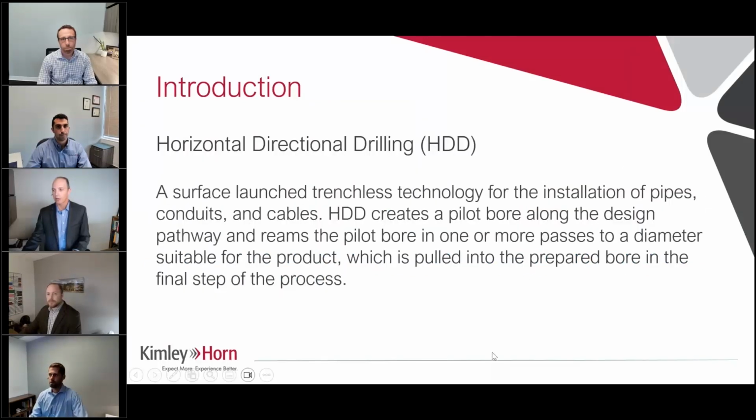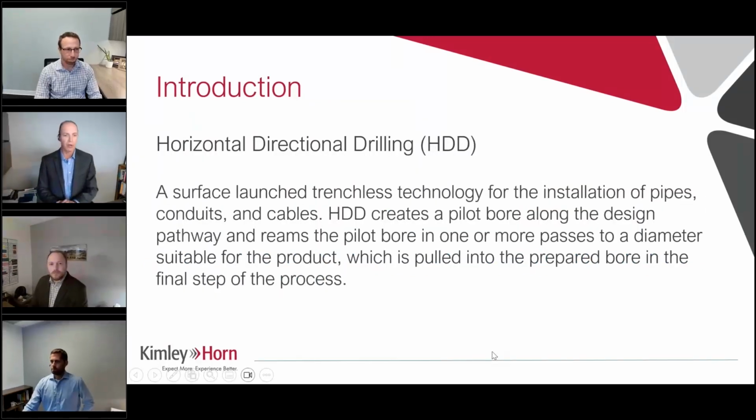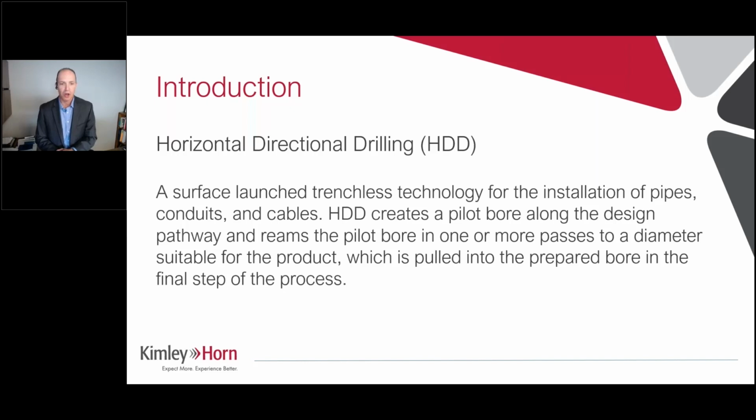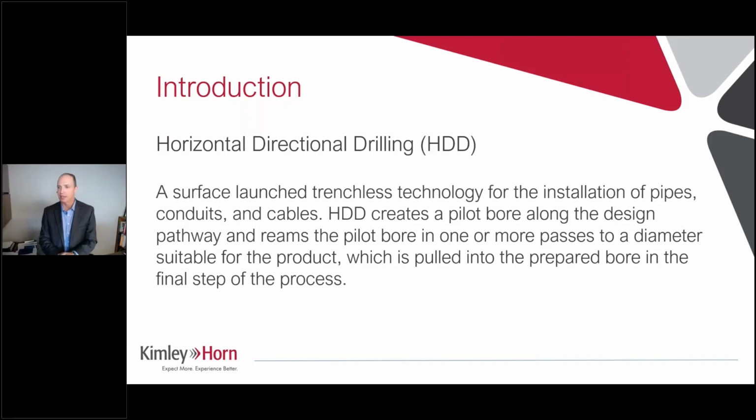As we get started, I thought it'd be appropriate to give a very brief definition of horizontal directional drilling. This is the official definition shown on the NASTT website. Horizontal directional drilling is a surface-launched trenchless technology for the installation of pipes, conduits, and cables. HDD creates a pilot bore along the design pathway and reams the pilot bore in one or more passes to a diameter suitable for the product, which is pulled into the prepared bore in the final step of the process. So that's a simple definition.